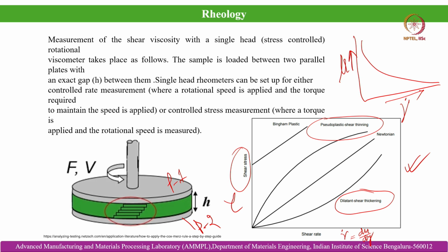As it flows through the intricate die cavity, through the runner, ingate, and also runner extension, there are chances of solid formation within that, and it happens in reality, and then suddenly the viscosity can go up.